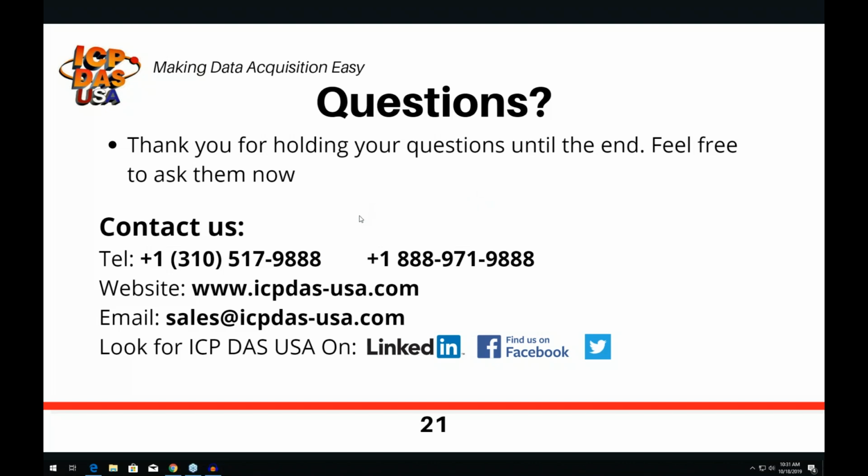That's already been answered, the difference between coil and holding registers. Are there any modules which are Class 1 Division 2 certified? Typically, no. Our modules are put into enclosures for these type situations. If you do require Class 1 Division 2, that's what I'd suggest. We don't have any modules which are explosion-proof at the moment or can be used in Class 1 Division 2 environments. We are CE only. We don't have UL.